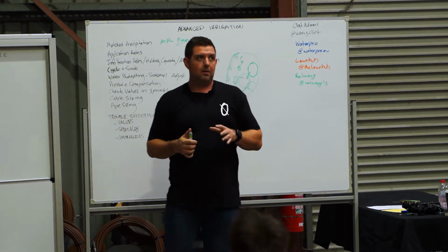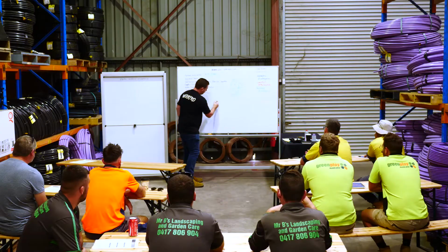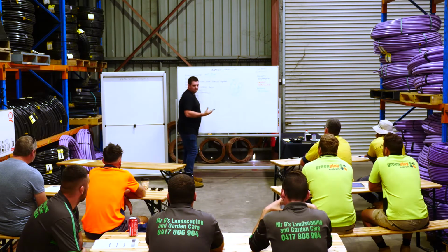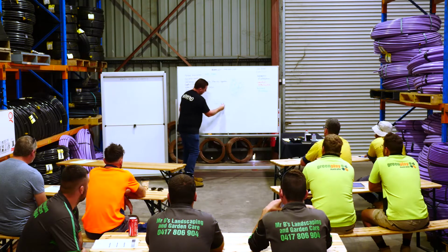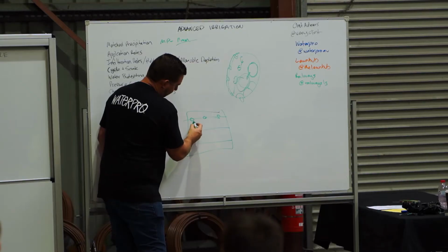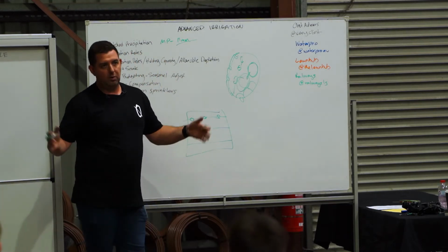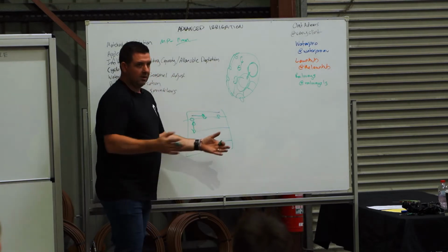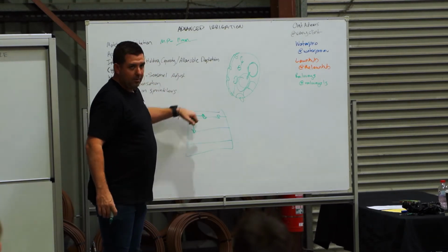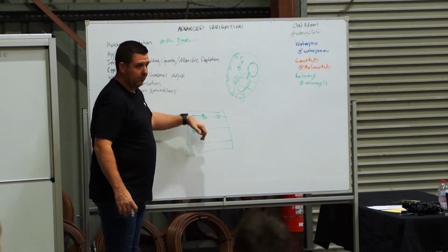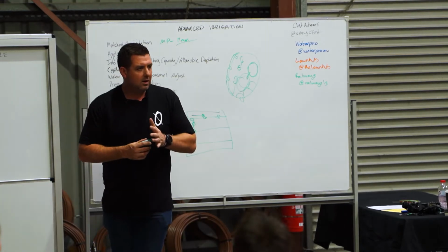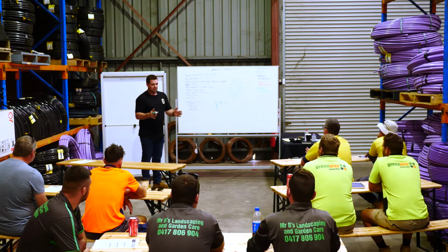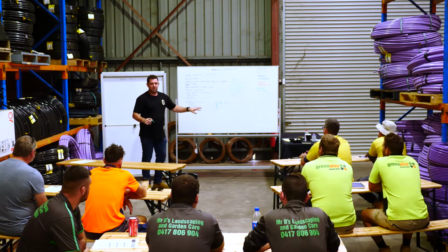So if you're looking to irrigate a garden bed and you're running drip line, as you would probably see in more densely planted areas, you've got a spacing between the drip line of a predetermined amount, so it might be 300 or 400 or 500, and then a spacing between the drippers, also predetermined, whatever comes on the roll. This can be 0.3 by 0.3, 0.4 by 0.4, 0.3 by 0.4, it depends on the spec. Any of you guys do commercial work, in a lot of those cases you're going to get a specification and that's it. You're working to that, you don't step outside those lines.